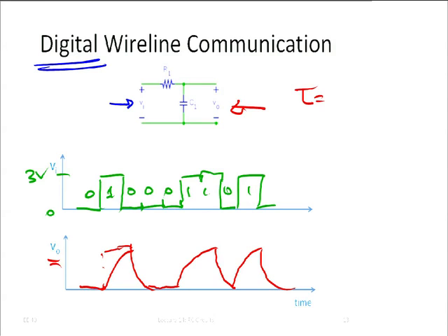How would you make the capacitance really small? Make the cable shorter, for example, or make the diameter bigger, or put the conductors further apart. How would you make the resistance smaller? Use a fatter wire.